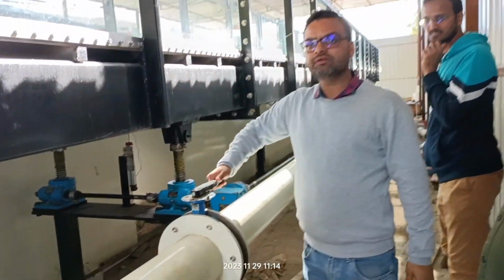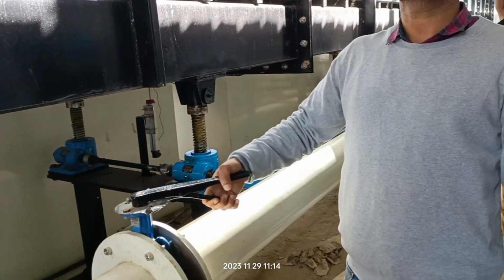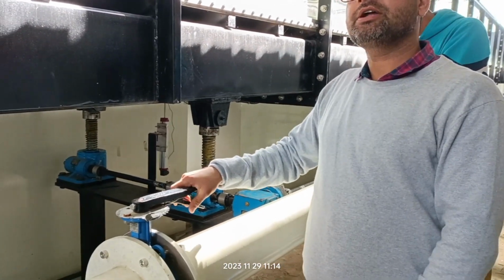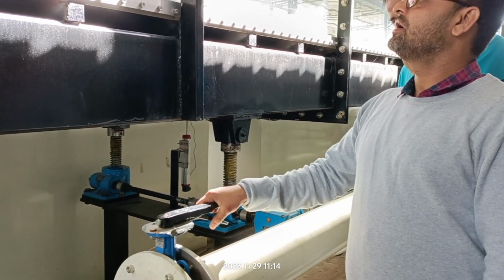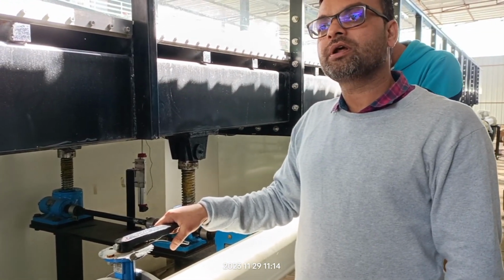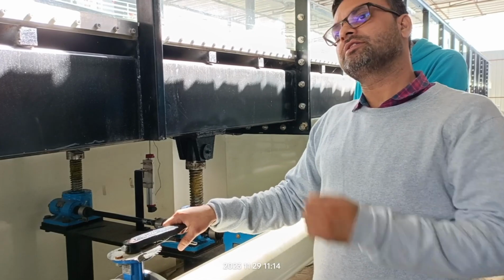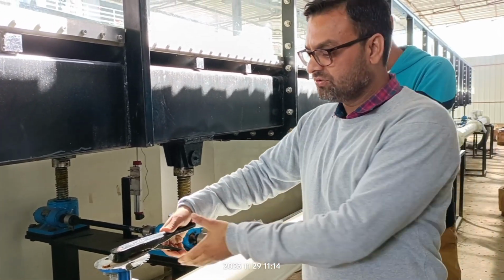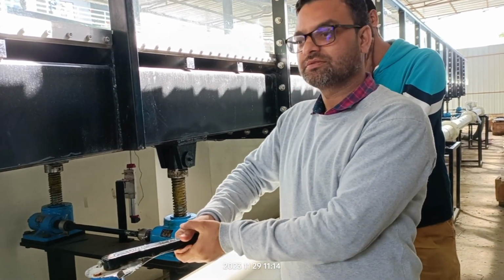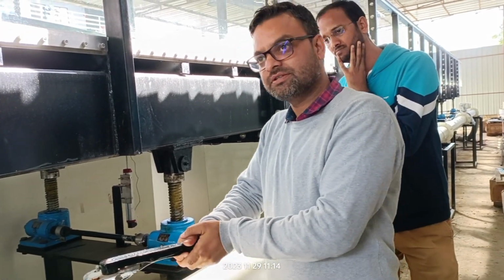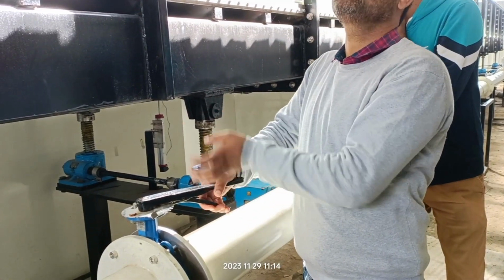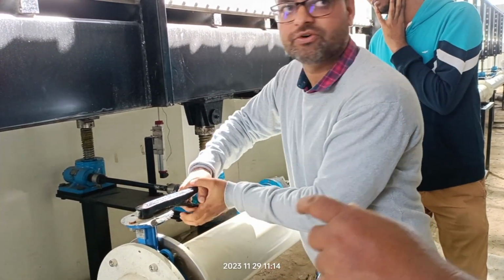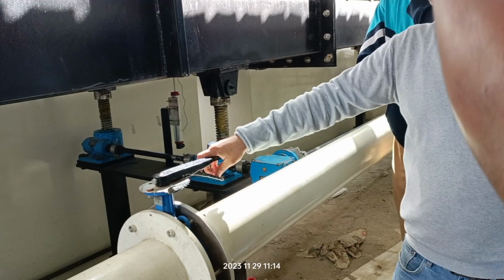This is for fine controlling. It may be possible that you want exactly 55 cubic meters per hour, but you are getting either 50, or 54, and then it jumps to 57, 58. So what will you do? Partially close this, and you can get exactly what is required. So whatever we are telling now, the display will show us 55 if you have this. Yes, surely it will show.